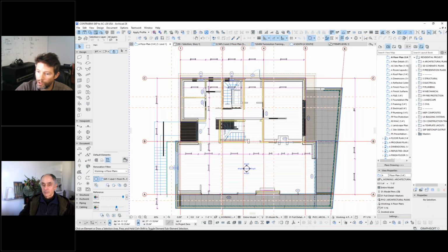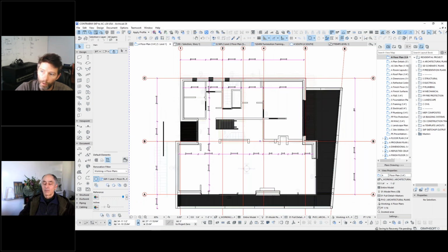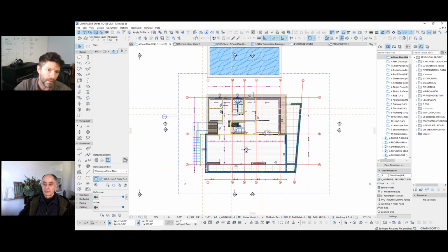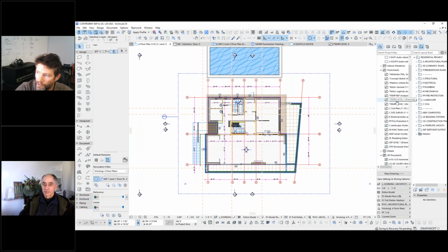So we can turn this on as a trace reference to be able to see our reference there. Or at other times, I may still take it out to a worksheet, use that to lighten up the load a little bit, and then trace and reference from a worksheet. Sometimes while working in ArchiCAD, if you have your trace and reference turned on to two different views, it can slow things down a little bit on the performance side.